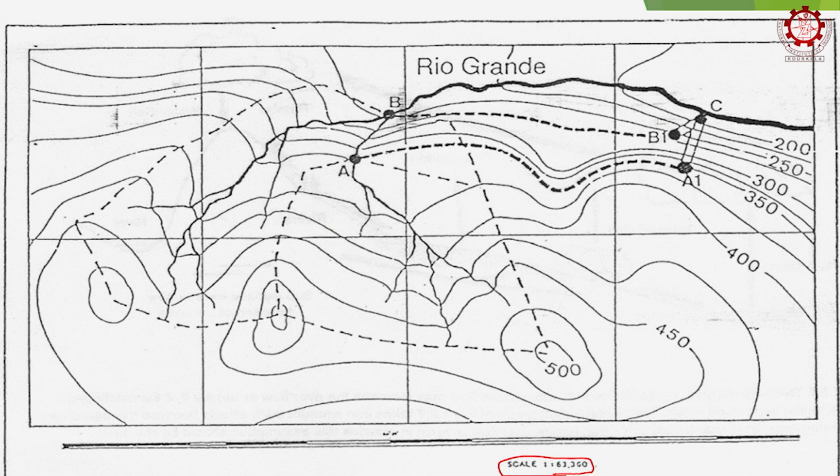We can see contour heights are given, these are all in meters, right. You can see here it is 200 meter, 200, 250, 300. So, you can see between these numbers there is one line here. So, therefore, it must be 300 and 350. So, this must be 325, right. So, now in this particular map between any two lines height difference is how much? 25 meters.